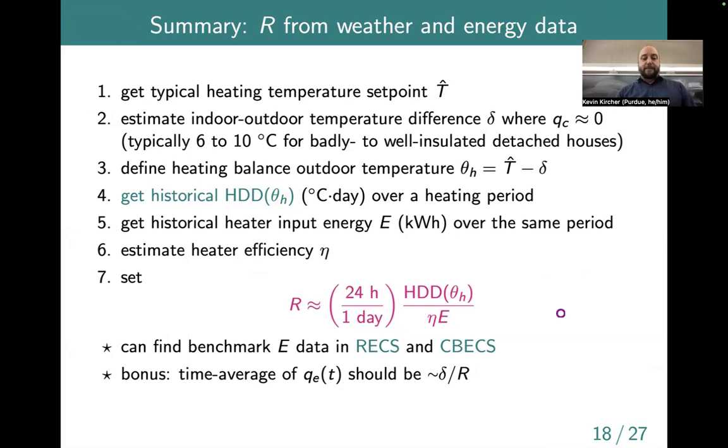All right, so last time we did our first lecture on thermal modeling of buildings. We talked about basically what goes into true first principles physical modeling of buildings, why that's pretty hard and maybe not super well suited to problems in designing and operating DERs. Then we talked about a simpler approach called thermal circuit modeling, which is a little bit easier and leads to linear and low dimensional equations that we can embed into things like optimization routines to help us with sizing decisions, operational decisions, and things like that.